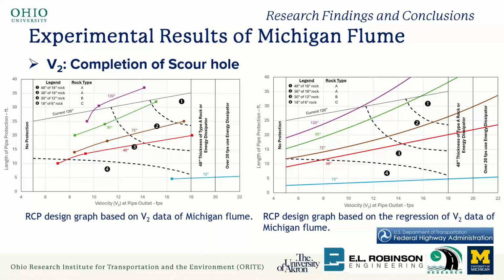Can I say something real quick, Danny? Sorry, this is Kevin. In general, the procedure used in the HEC publication is fairly conservative in the sense that it only looks at a native material and determines what the scour hole of that native material is, and then just fills it with stone. That's how they come up with those lengths. So generally speaking, the HEC method is somewhat conservative.